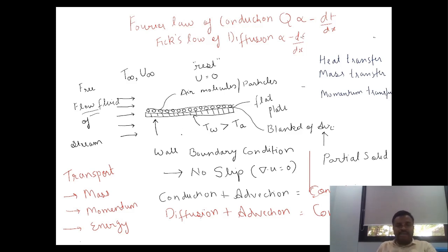So these convection diffusion equations are merely mass and momentum equations. We need to solve the mass equation, that is the continuity equation, and the Navier-Stokes equation, to get the solution for problems belonging to convection diffusion, CFD oriented. So we have this framework: heat transfer, mass transfer, and momentum transfer. But in this chapter we will be focusing on heat transfer and mass transfer. Momentum transfer can also be used to solve convection diffusion problems, but it will be considered a different framework, not under this one.